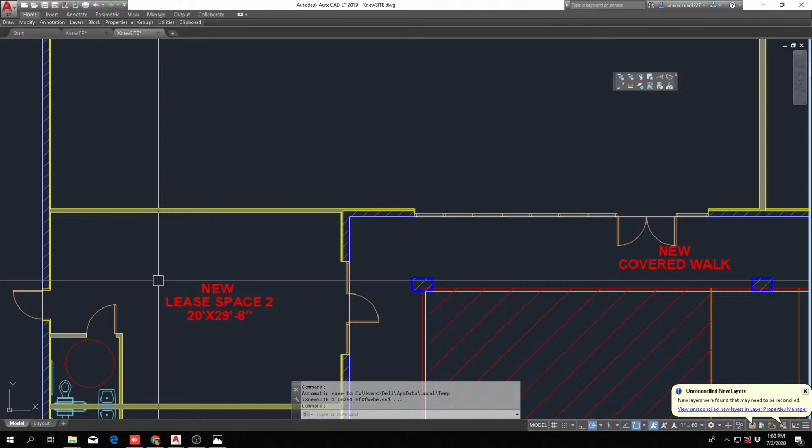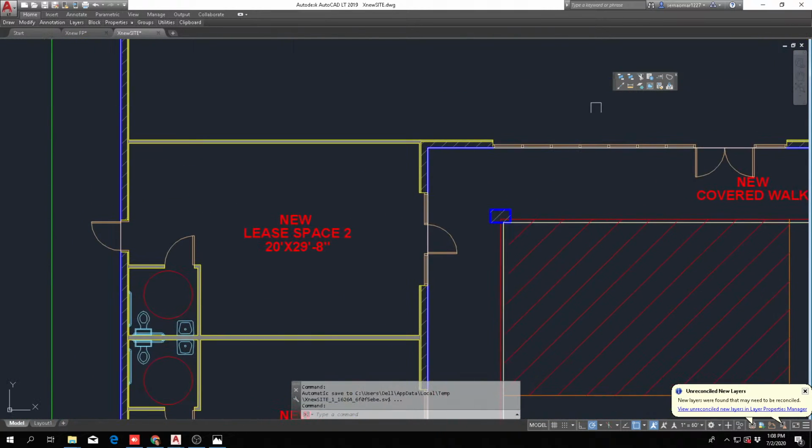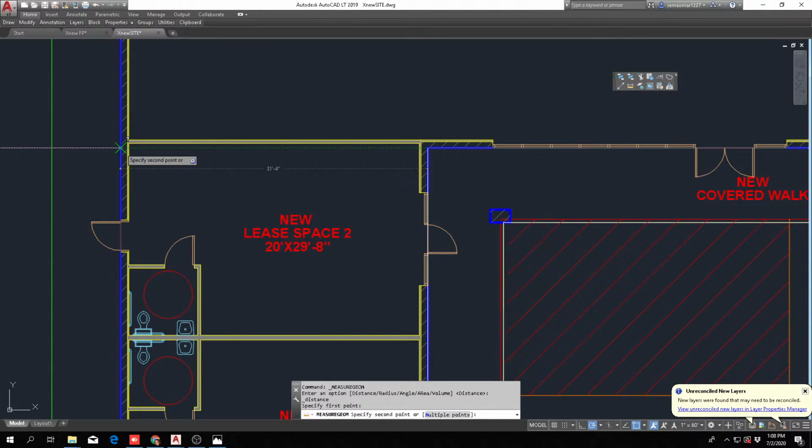It's about a foot every 10 feet or something like that. So in this case, since I'm spanning 30 feet all the way, 32 feet of it, 31 foot 4 across, the joist might be about 31 inches thick or deep, 31 inches deep.